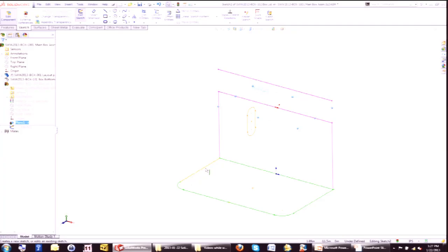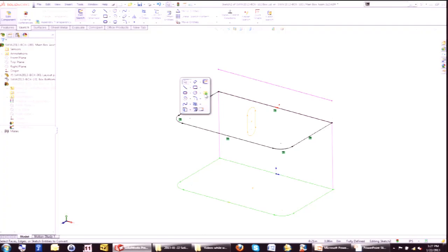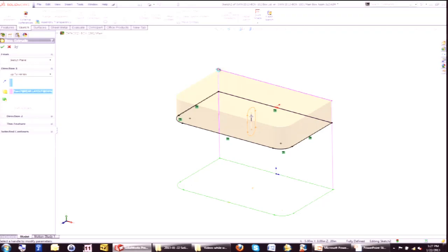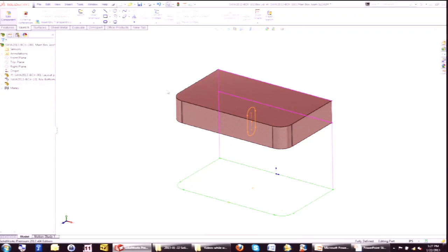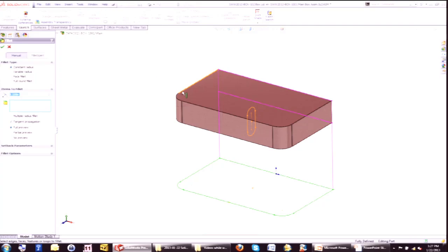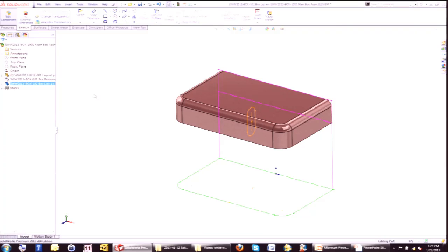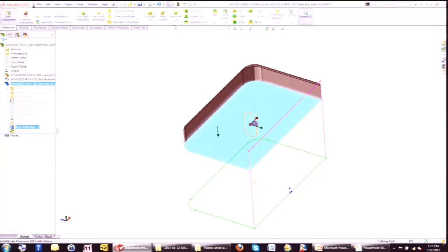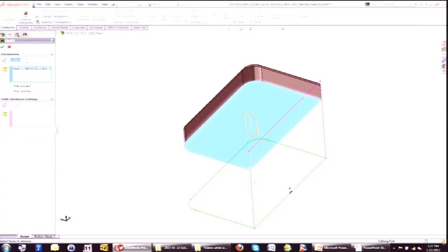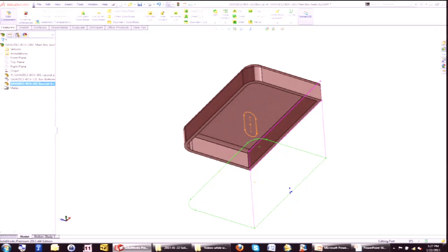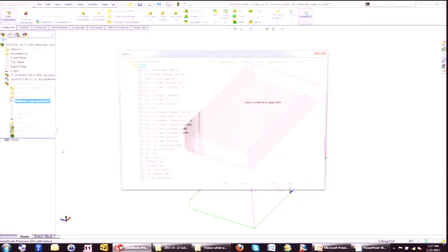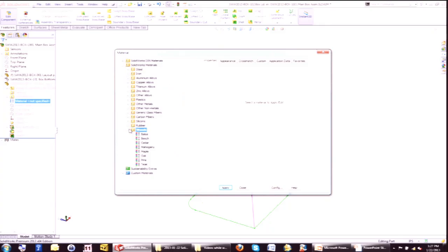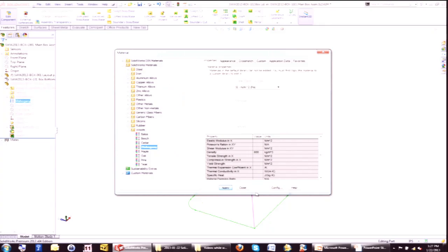So select that plane, begin a sketch, right click, select chain, convert entities, S key, extrude up to this point here. All right, and that gives us that feature. Maybe we're going to add a fillet on this edge of the feature, 1/2 inch. You notice the dimensions for that fillet weren't part of the layout. That's fine. Everything doesn't need to be included in the layout, just the key overall dimensions. And then I'll do a shell here at 0.25 again. Just like last time, maybe I go in and assign a material. So this material is going to be mahogany.